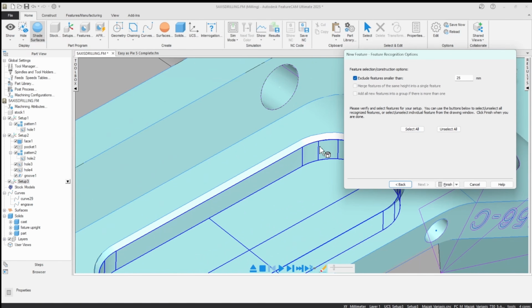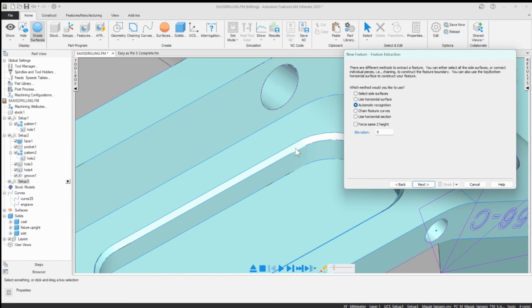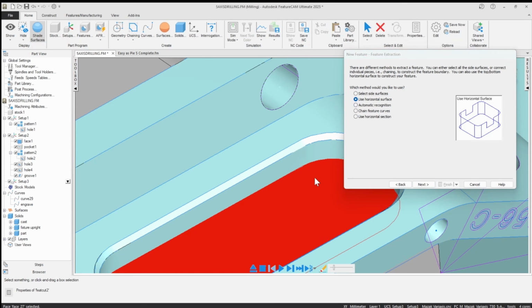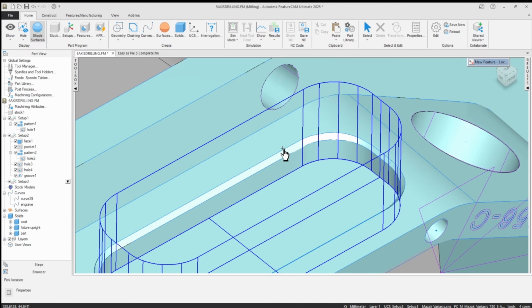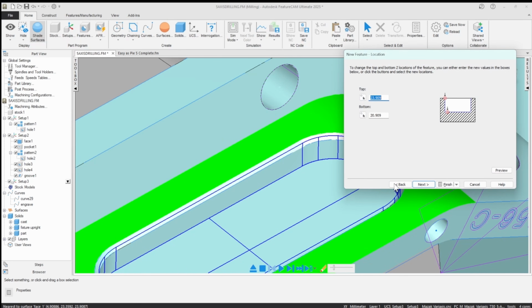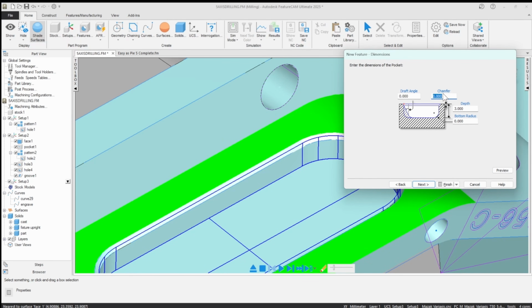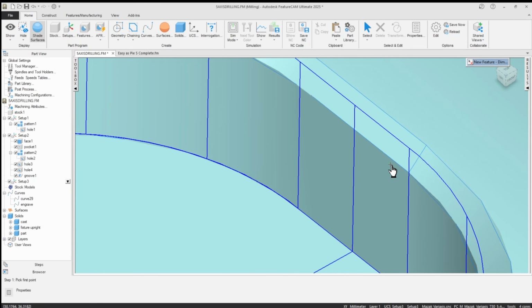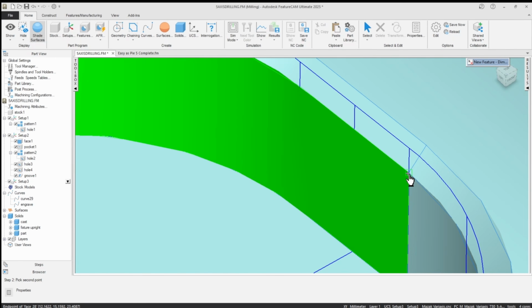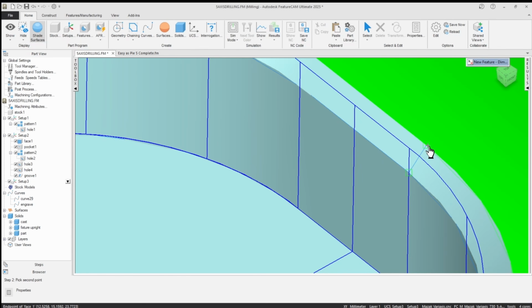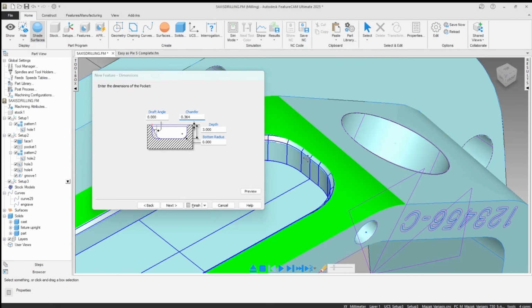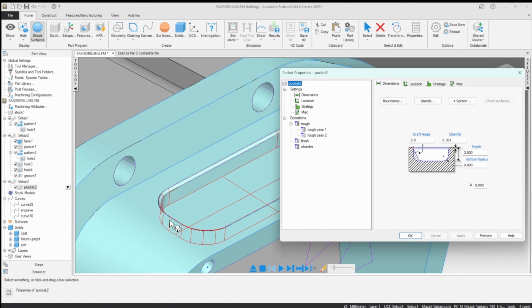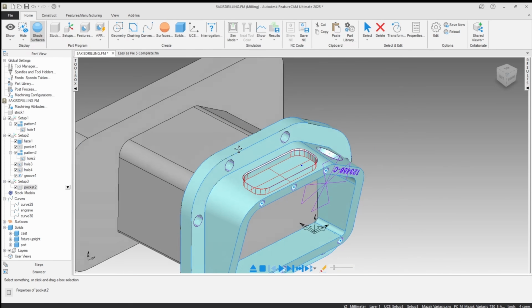Okay. Now when they have chamfers, this won't include those. So what you want to do instead is use one of these methods. Okay. And then you want to set the top here, and the bottom will be good. And then if you don't know the chamfer, if you can find a seam, like I can see one right in here, I can snap here to here, and it will pull that chamfer for me and make the chamfer on the part. Okay, so pretty simple to do that.